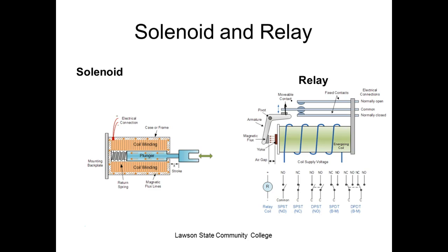So that relay inside your box that you hook up there to replace your light switch is using DC, but it's controlling AC. We're doing it with a what? Odds are if you went over there and listened, you would hear a little click, which would be the relay actually picking up. You can actually hear the relay. So we could be using 24 volts on the coil, but we could be controlling 500 volts on the contact. So we can change the type, we can change the voltage level through a relay, but what's nice is we're controlling relays with electricity. As soon as I say electricity, we can turn it over to automation, right?